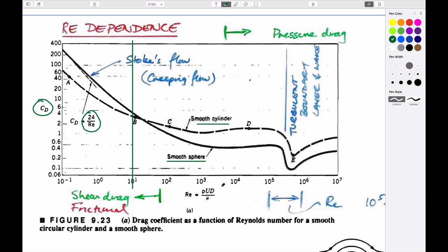And as you get into the turbulent regime, you move from a shear drag region, you can choose where that would be, to a pressure drag region occurring here. And it's exactly the same behavior that we've looked at in these. So the bottom line is that we can define these regimes which are laminar and turbulent. There are different dependencies in each of these in terms of the role of shear drag versus pressure drag in different parts. And ultimately, this affects the calculations that we will do.